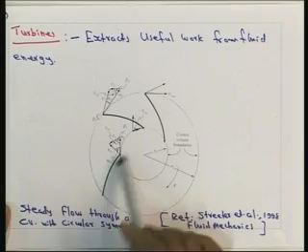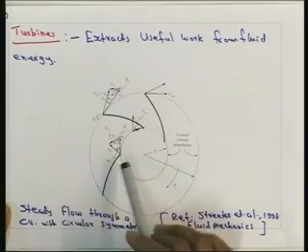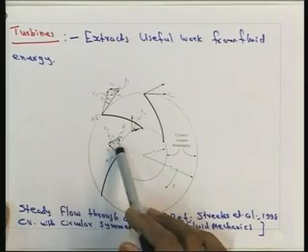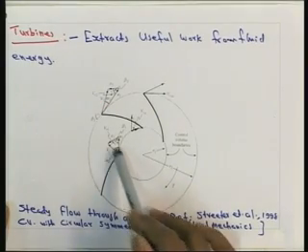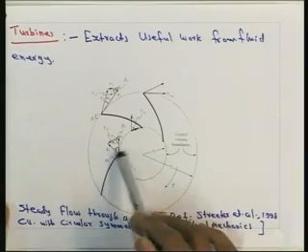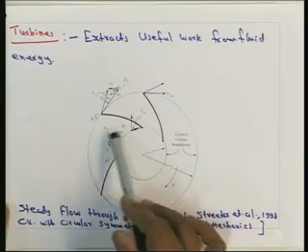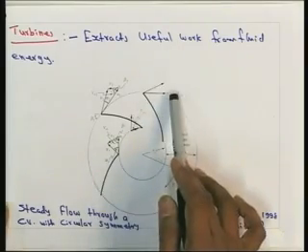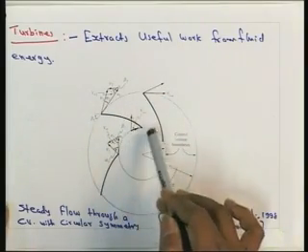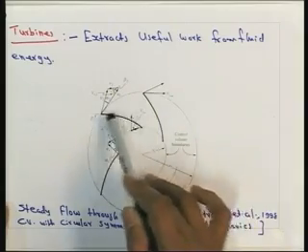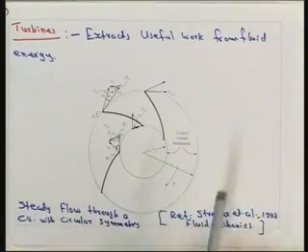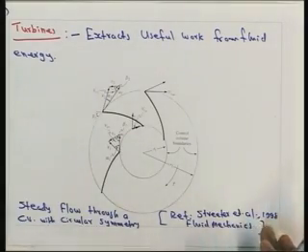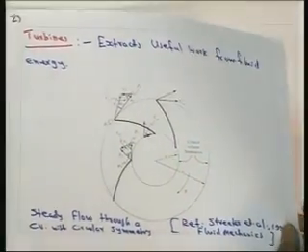If you consider a particular blade where the fluid, either a water jet or any other kind of fluid, is hitting, here alpha 1 is this angle, and V1 is this velocity with respect to the blade, and VR1 is the radial velocity. You can see that we can have a tangential component and also the radial component. With respect to this figure, how to apply the moment of momentum equations is what we will be discussing here.